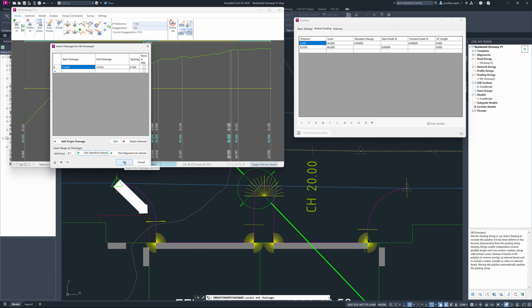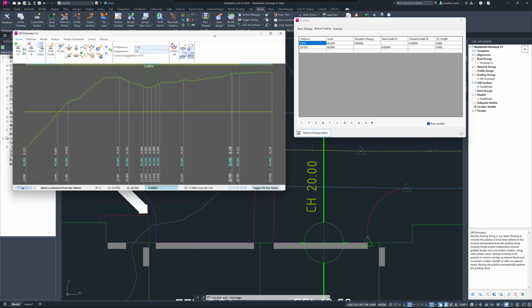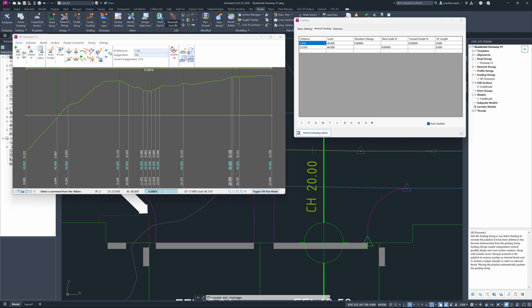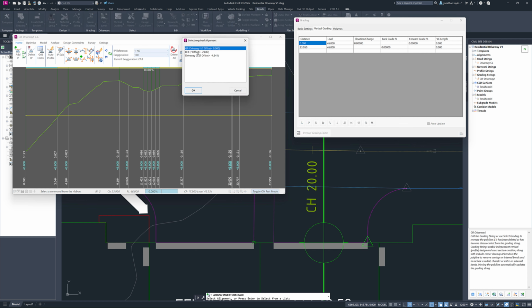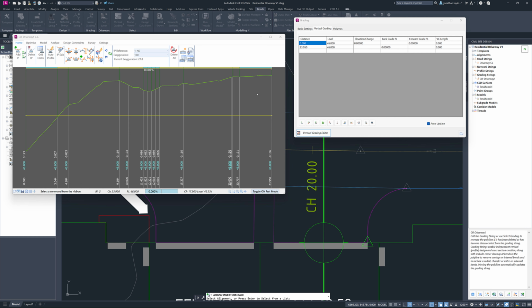I can click OK. If you're not using version 26 of Civil Site Design, you would have to manage this a slightly different way. You'd have to come up to the Roads tab, Edit Panel, click on the Resample section pull down, and then click somewhere near or on top of your grading string, and that form will then display, whereas 26 users now get that at the right click of tool space.